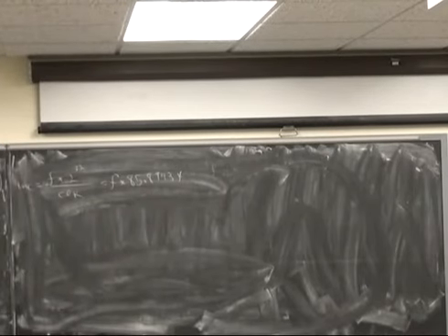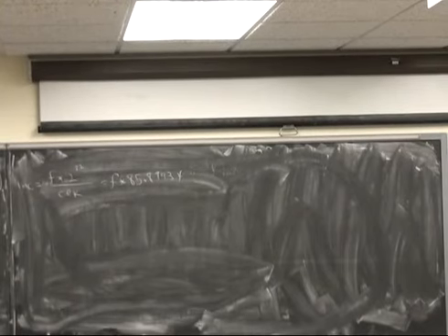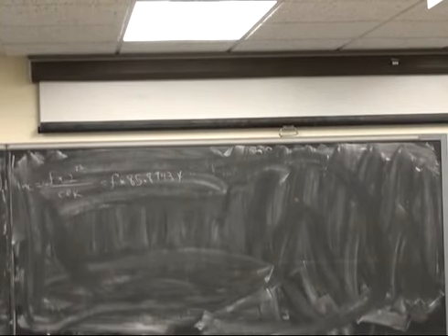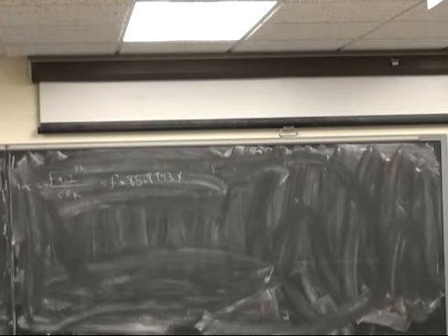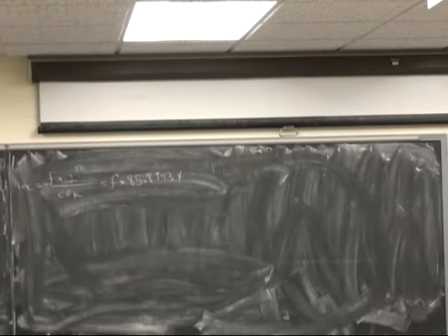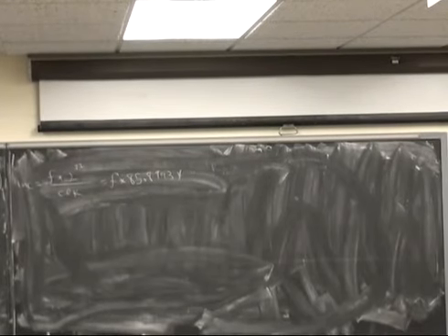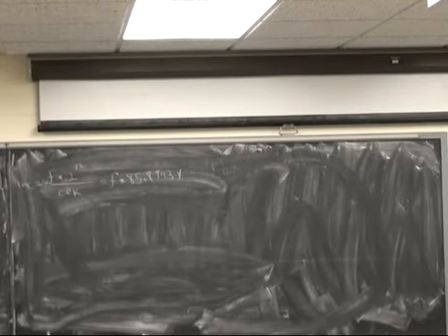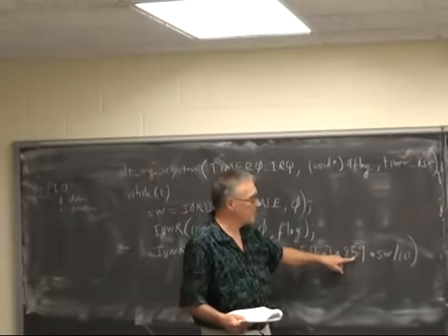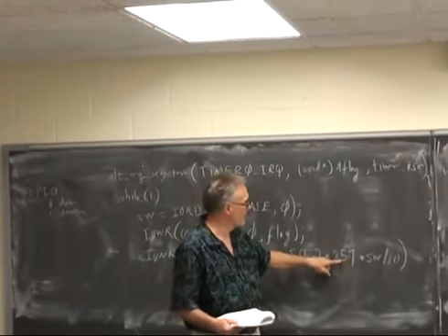So what we're going to do here is multiply by 859, because I didn't want to use floating point arithmetic, times the switch. So we're using the switch to offset the frequency, and we're going to divide this by 10, which makes it equivalent to multiplying by 85.9.